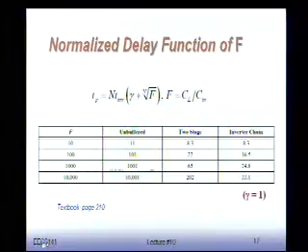Okay? Now, it's interesting to see how much impact you have by using this optimal sizing. And I just show some very simple examples here. Suppose that I have to drive a capital F which is equal to 10. So it means my input capacitance ratio to the output capacitance is 10. Question is, how many stages should I use for the optimal delay? And what is going to be your optimum delay for that particular case?